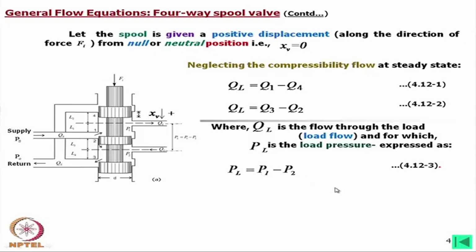Now, in this case again we normally use a symmetric actuator, which means we have a rod end at both ends of the piston. Normally for servo valve actuators, in both directions the rod end is there. So, the area is the same in both directions. Okay. Normally it can be otherwise also, but it is normally like that.